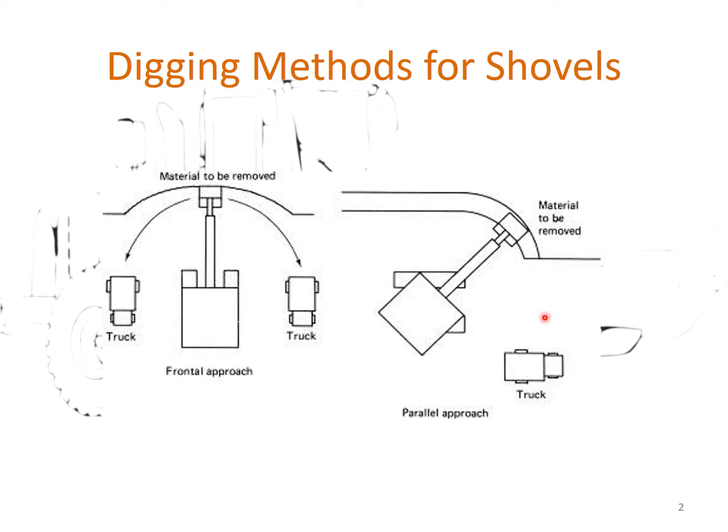So with that one, we are able to reduce the swing angle from the location of the excavation to the dump truck. When you reduce the swing, you tend to increase the capacity, because the cycle time will be reduced for the shovel. So that's one way to improve efficiency.